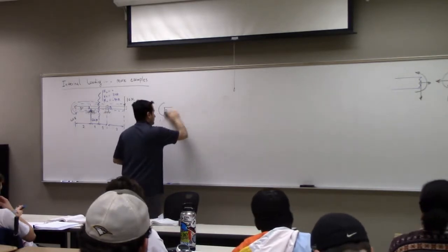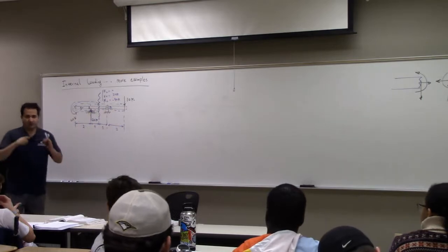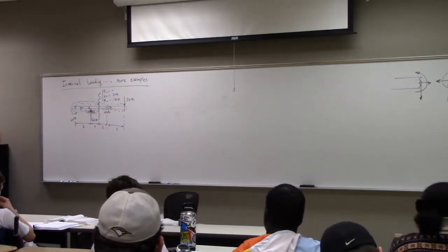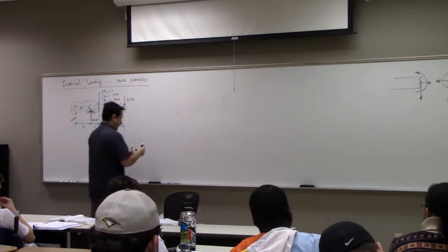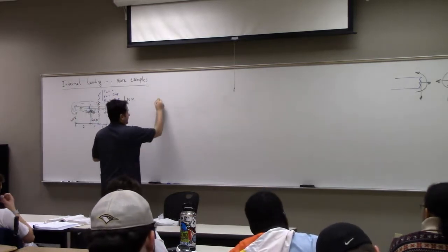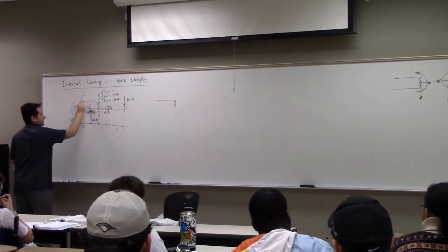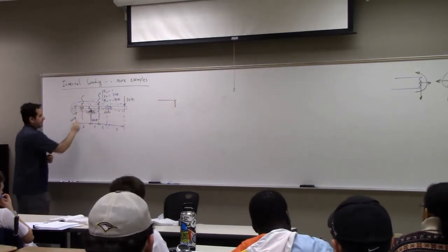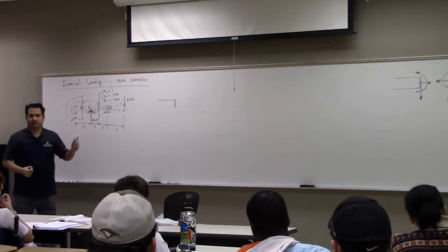Again, the motivation to do another point is just to see the trend, and then from the diagram you guess what point is the maximum, the critical point, right? So at point D, if I want to find internal loading, I just cut it like that, right? And in this case, I prefer to take the one on the left. Why? Because it's simpler.